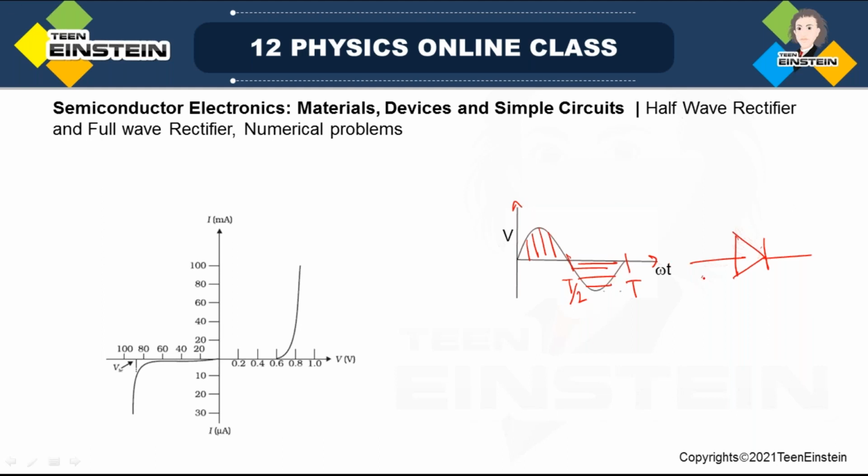In the first half cycle, this terminal P will be positive, and in the next half cycle P will be negative. That means in the positive half of the cycle the diode will conduct, and in the negative half cycle the diode will not conduct.